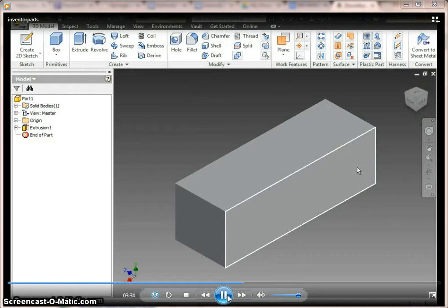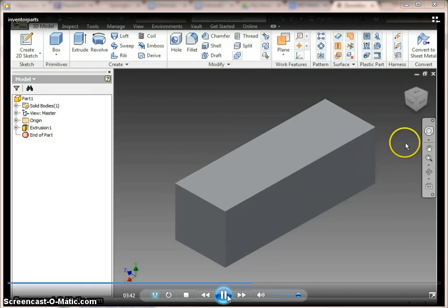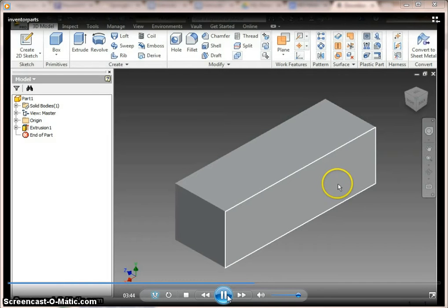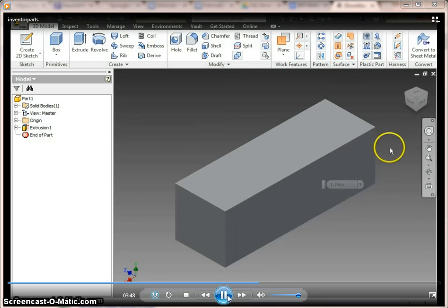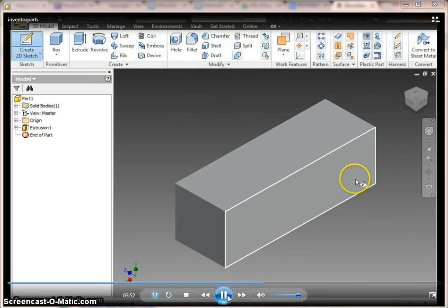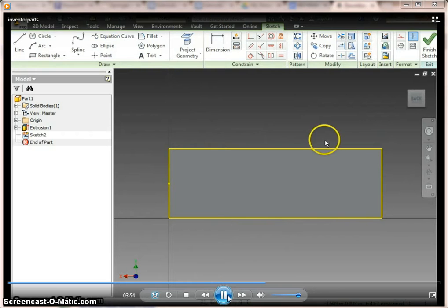And what I'm basically doing is on the part, I'm going to be putting a square at the last edge, and I'm going to extrude it out, and then that'll give me a surface that I can extrude and make the rest of my piece. So I do a sketch plane using the face, and then when I select the sketch plane, eventually, it's a 2D sketch, there we go, okay, I'm going to see that face, and it's going to do yellow lines to indicate where the geometry has been projected to my sketch plane.